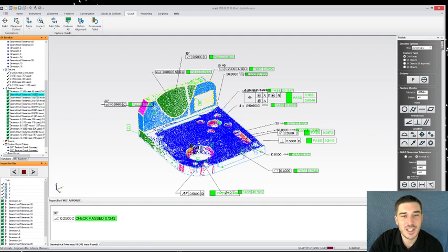So it's just a really concise way to show each feature check, the icon for what it represents, the tolerance, and then the high, low, and all of those things, pass, fail, and also the deviation in and out of tolerance. And then if you have a true position check, then you also get a direction error for the direction of deviation. And it shows up green for pass, and you get an indicator of that as well.